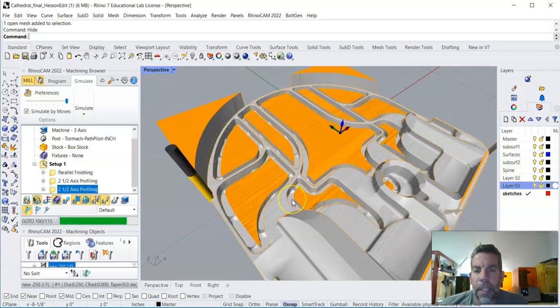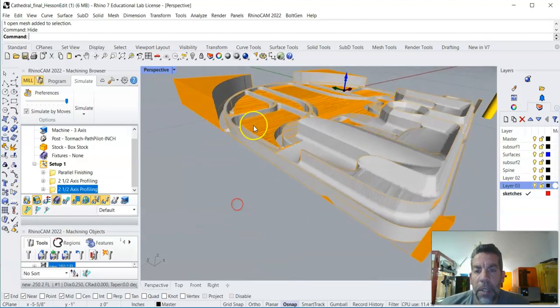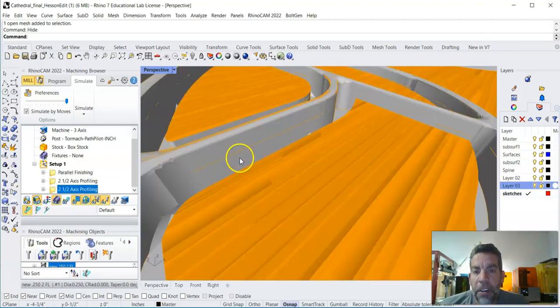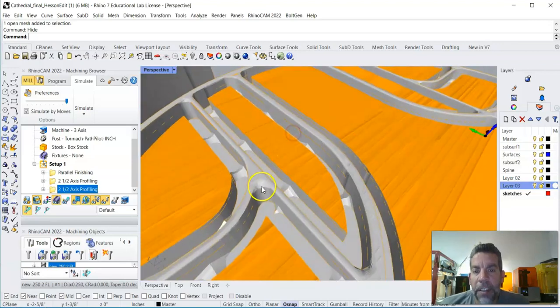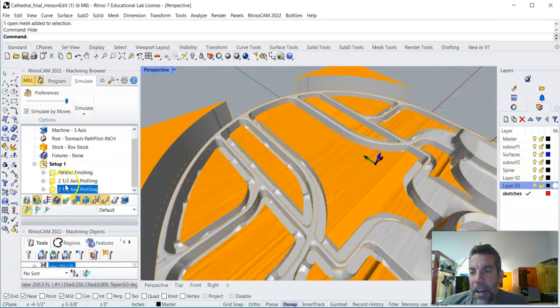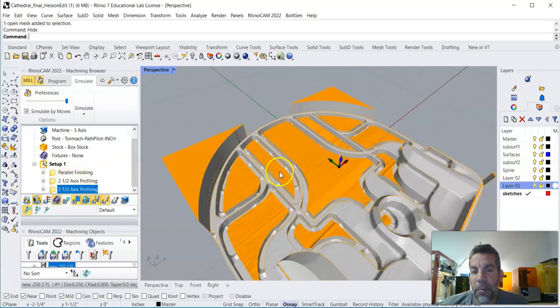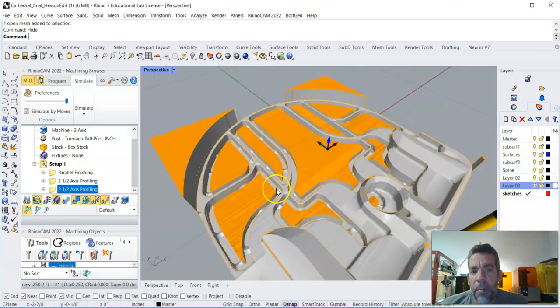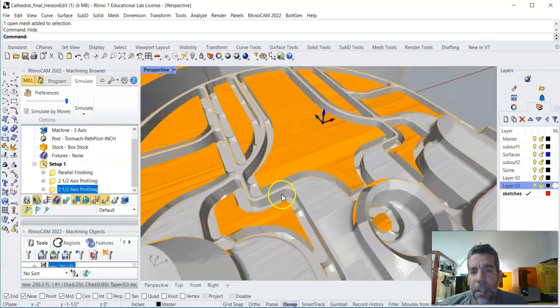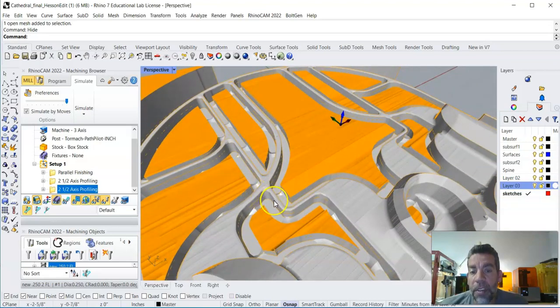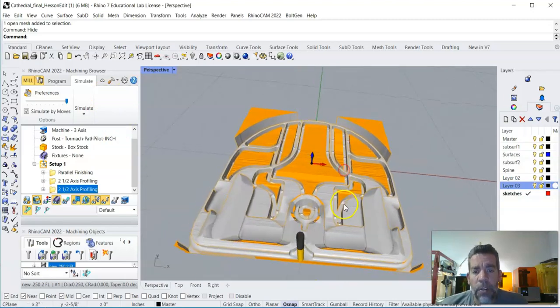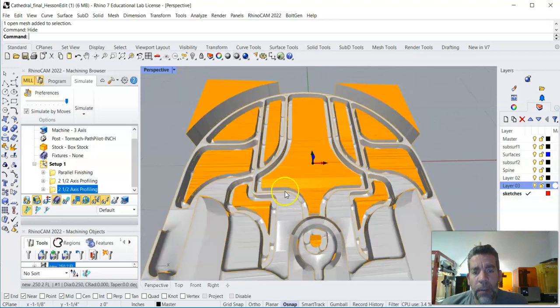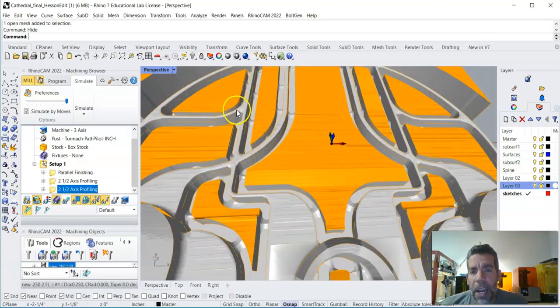Okay, so you can start to see then, and then we'll do this outside. So we can start to see that we get a much cleaner finish. Now, is it getting as deep as it should? That's where you probably want to switch out. The 2.5 axis profile would probably be a smaller diameter if you want to make sure you're getting way up into those corners. But I don't know that you have to use a teeny tiny bit. Again, it just depends. But it'll still give you a clean cut. It just may not match your geometry exactly. So that's where you change to your smaller bit if you want each one of these radii to be specifically exactly what your file was.